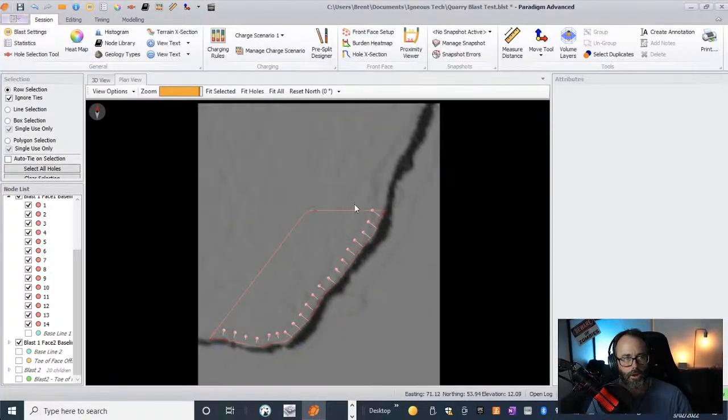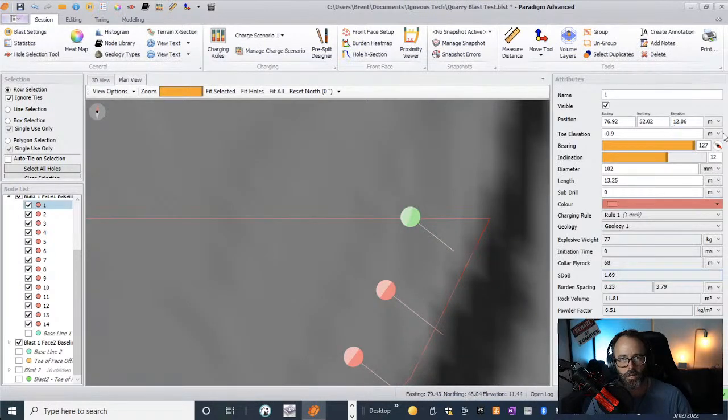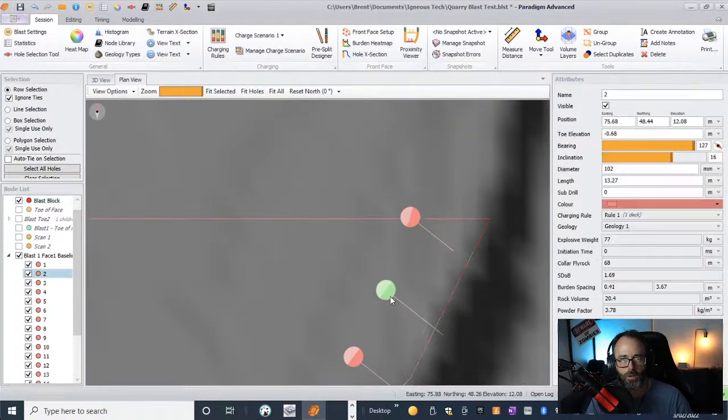So that's one way of doing it, which is saying, well, this is 12 degrees. Let's just check that. 12 degrees. And so if we were to put a hole directly behind that and ensure that it had a 3 meter separation, our hole would be only 1.4 meters behind it. So if we were to put it directly behind, it would be considered a helper or a lifter. This one is going to go across here. But because this value here is greater, this one is a